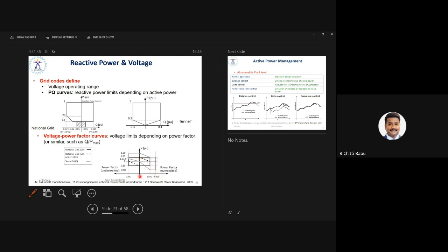Right. So for voltage, as the power factor reduces, the voltage decreases. But on the other hand, if the power factor is about 0.925, you see the changes in the voltage. Of course, it reduces below 0.95. It needs leading reactive power, so it needs power factor improvement. That is why we use over excitation, so that it is able to bring the power factor back to unity.